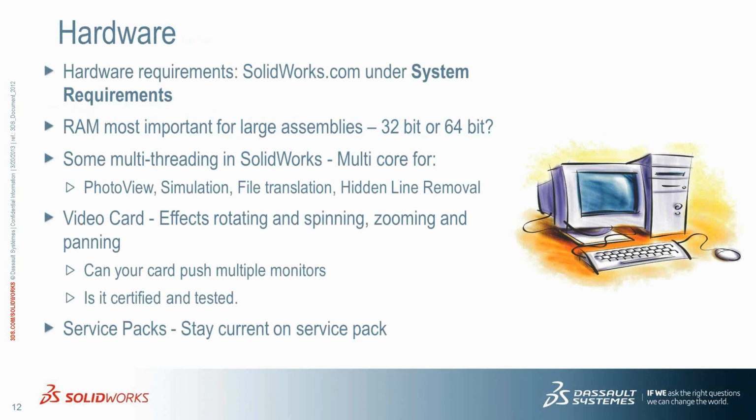Now, a little bit about the hardware. Hardware does play a role in the quality of how your large assemblies are going to run. I would say make sure, first of all, that you've met the SOLIDWORKS system requirements under solidworks.com. If you're running a 32-bit machine today, it's too slow. It can't access enough RAM. You really need to be on a 64-bit machine with a 64-bit operating system. I know SOLIDWORKS supports 32-bit, but 64-bit is the way to go and where you need to be.